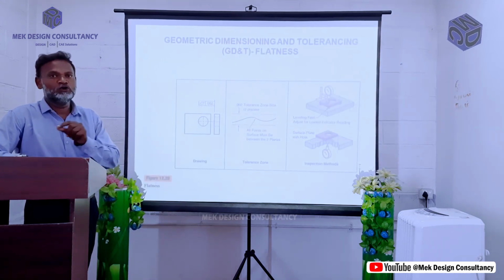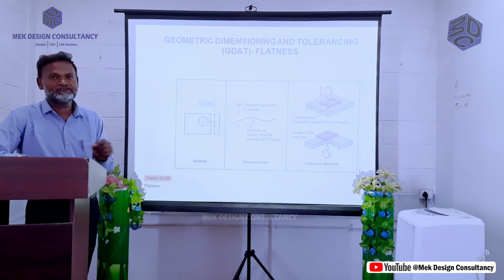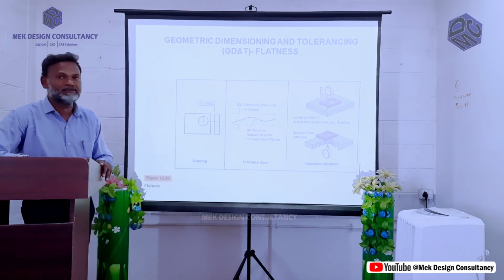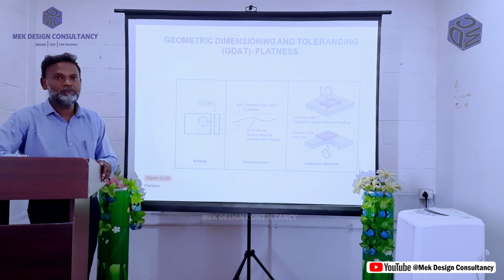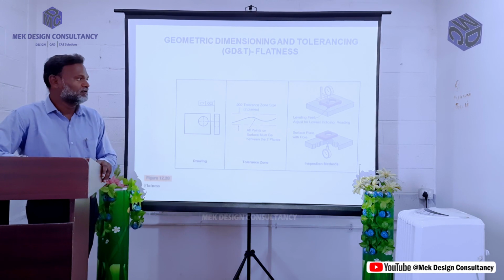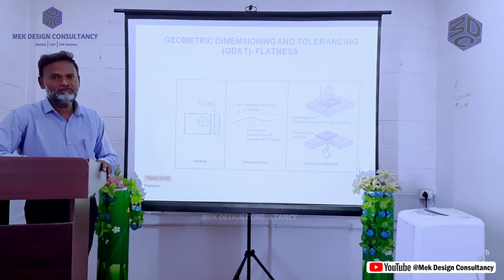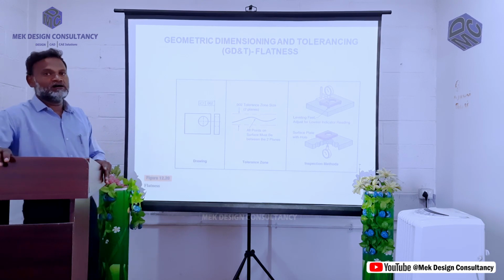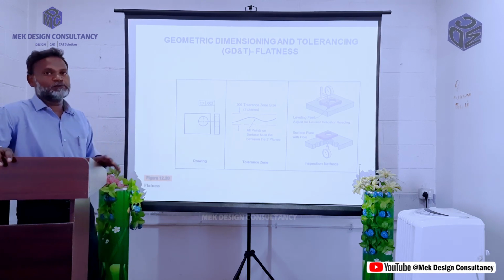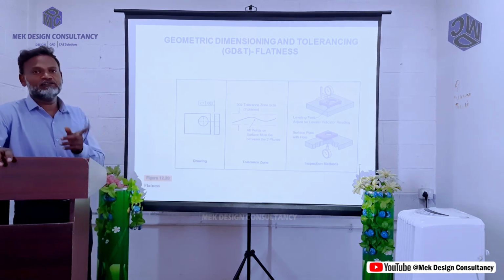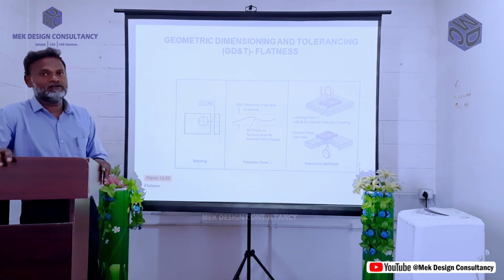So you can move the component either in the forward direction or backward direction. We should maintain the tolerance within the limit like 0.002, maybe on the plus side or the minus side. Okay, so this is how they measure the dimension. If the product is within the tolerance limit, then the product should be accepted and it will go for dispatching, right?